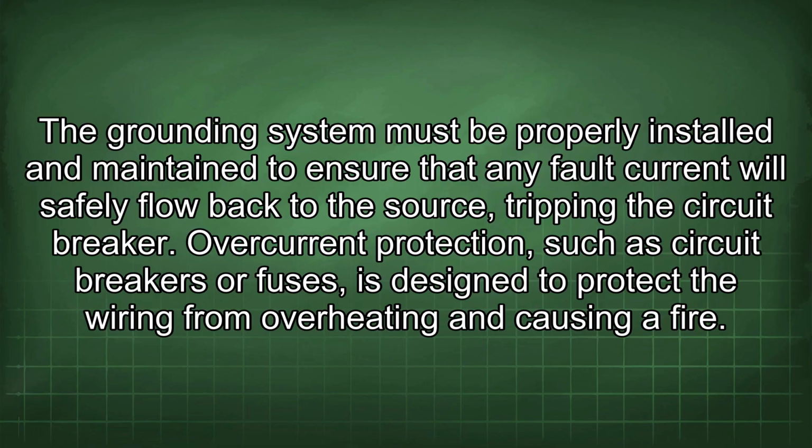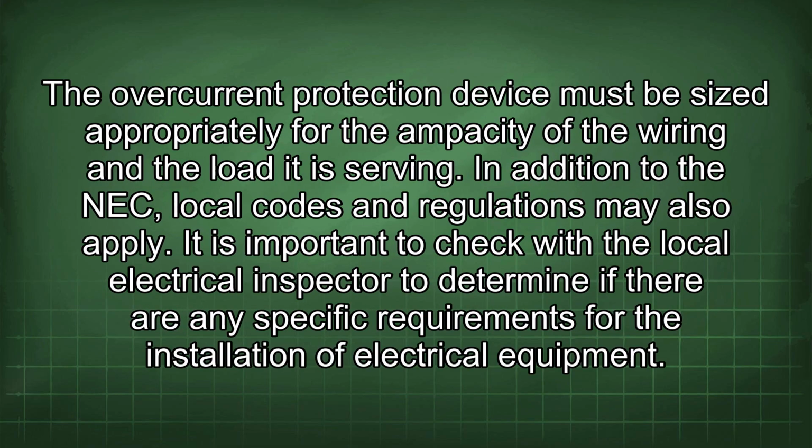Overcurrent protection, such as circuit breakers or fuses, is designed to protect the wiring from overheating and causing a fire. The overcurrent protection device must be sized appropriately for the ampacity of the wiring and the load it is serving.